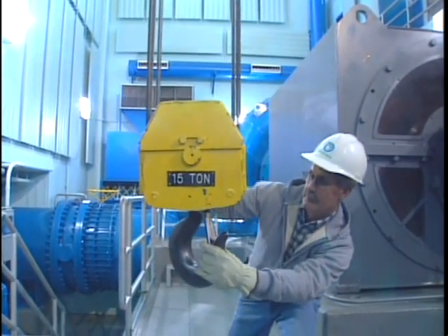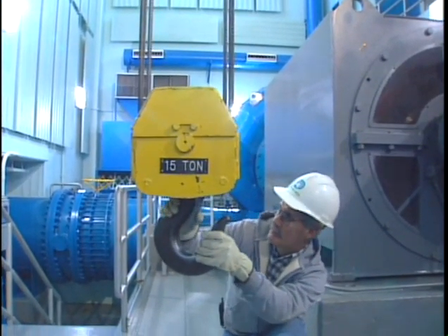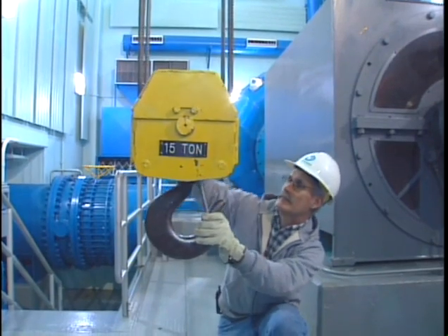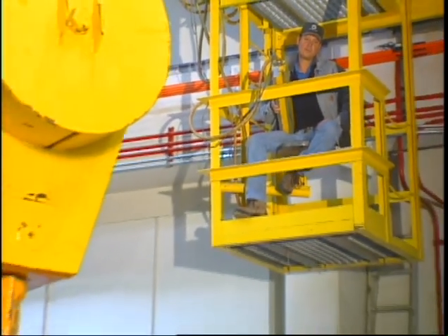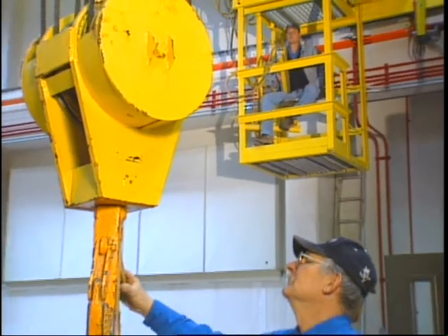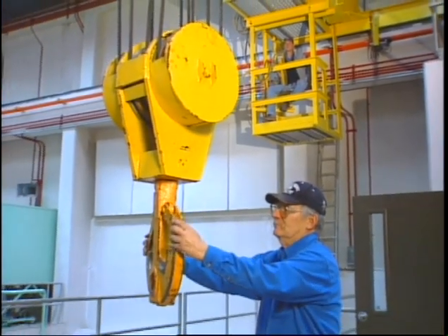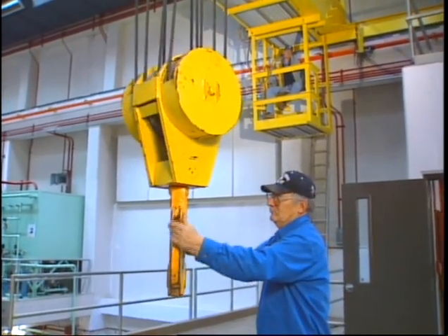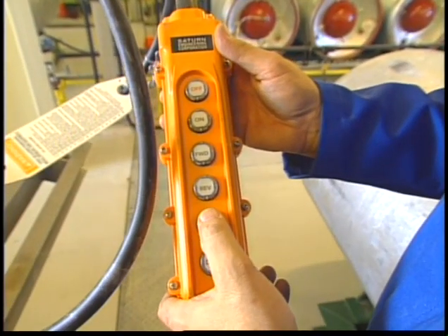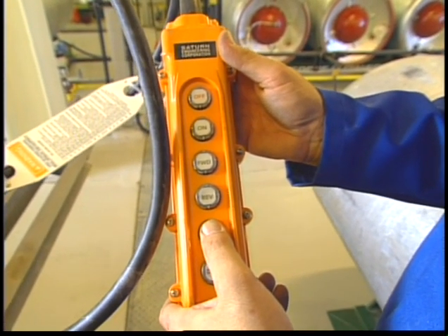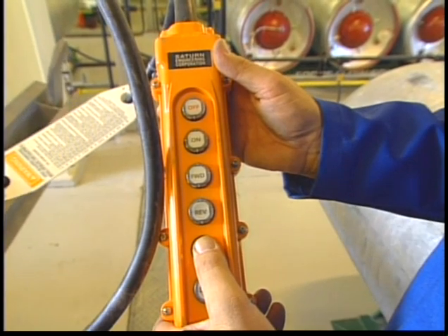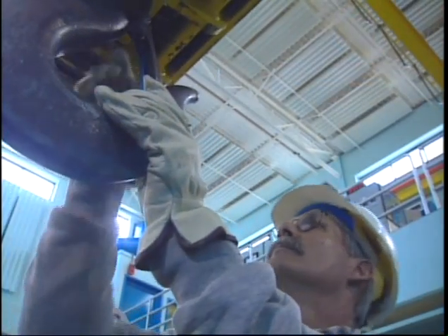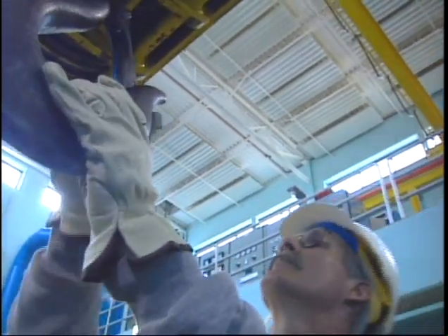Before ever using the crane, the operator and crew should inspect the equipment to make sure it's working right. This is an OSHA and American National Standards Institute requirement. Inspections are categorized as frequent and periodic. Frequent inspections take place daily to monthly. Daily refers to the fact that the operator should visually examine the equipment at the start of each shift.